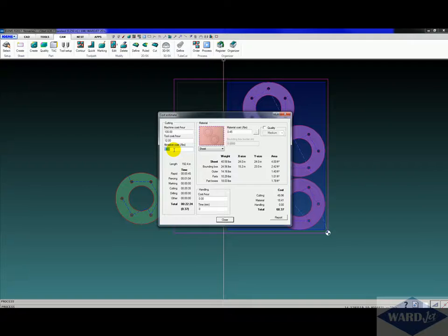And then you've got your cost, what you're paying for abrasive. You should also factor in some disposal cost into there. So if you're paying 25 cents per pound for new abrasive, you might be paying another maybe 5 cents per pound or whatever to dispose of it. So you should factor that in there.